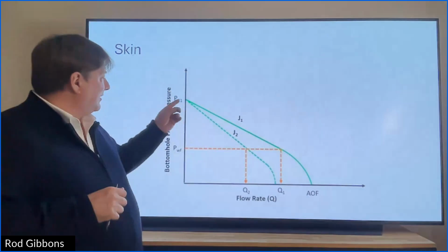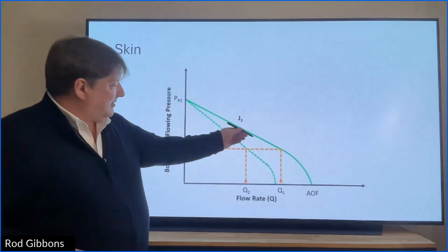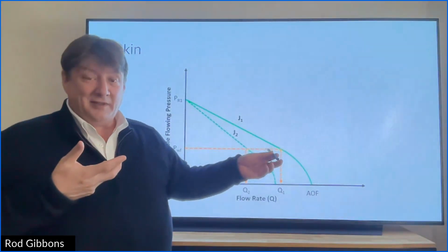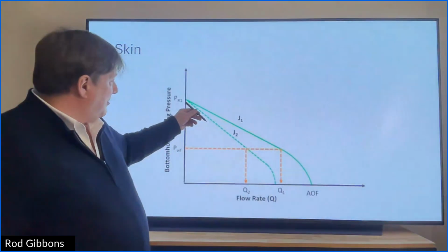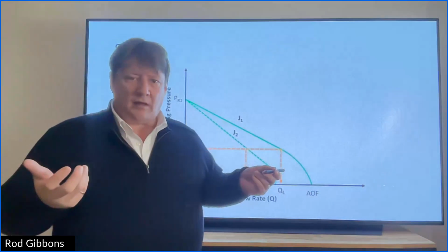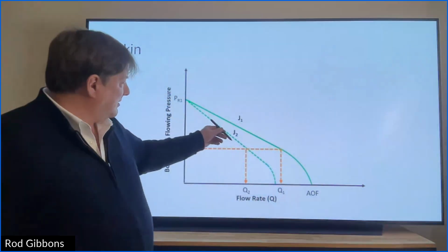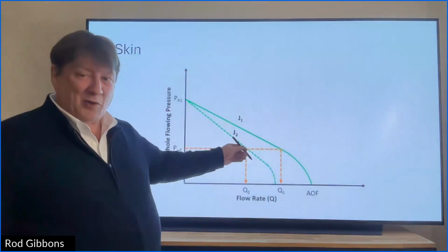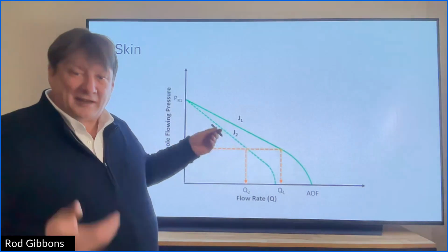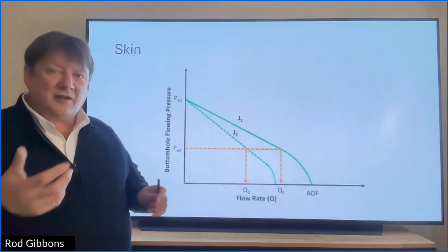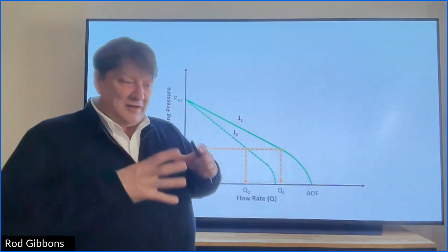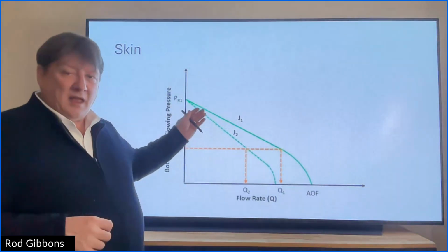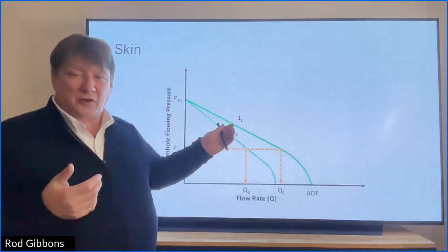We can draw that graphically. Again, if this first line is like a fire hose of oil and gas, but then a week later we shut in, we're still at the same reservoir pressure, but when we open it up, it doesn't flow very well at all. It's like a garden hose. Then chances are there could be some damage to the wellbore, which is referred to as skin. So that's one of the things that inflow performance relationship can help us diagnose.